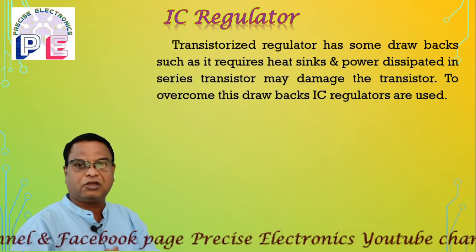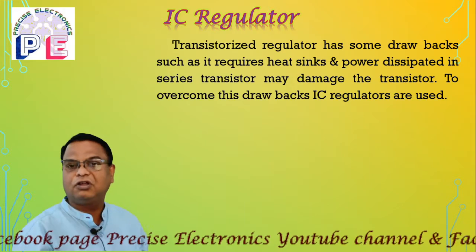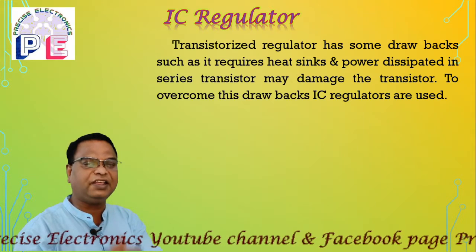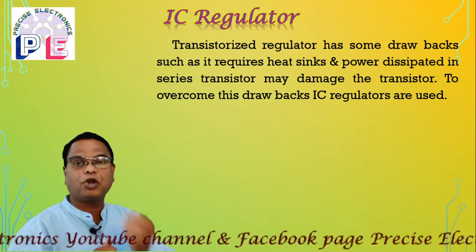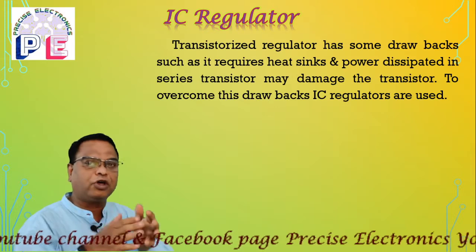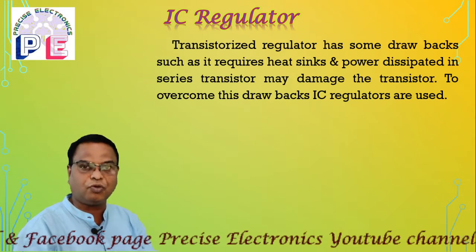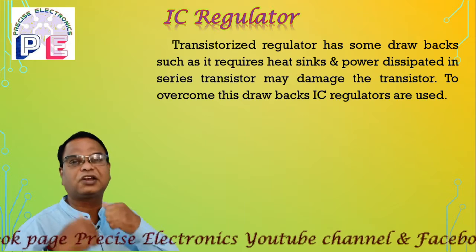This drawback is removed by using the next type of regulator, that is known as the transistor regulator. In the transistor regulator, the load current increases. But in this case, the series pass transistor has to dissipate a large amount of heat, because all the load current passes through that series pass transistor, and as the load current is very high, in the range of some amperes, 1.5 ampere is the load current available in transistor regulators.